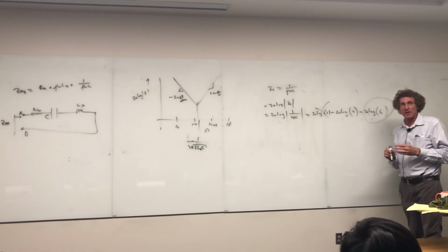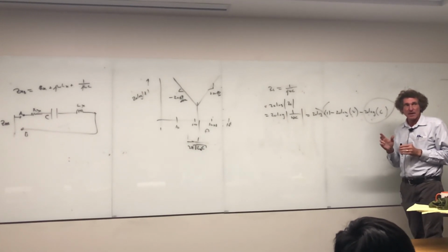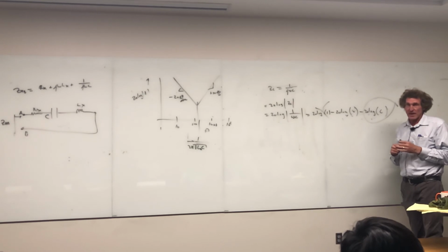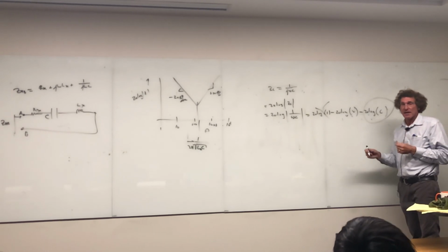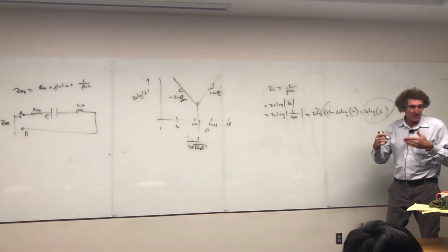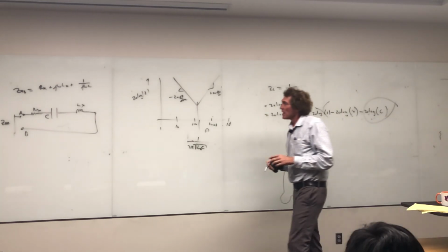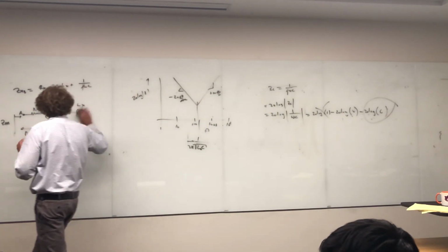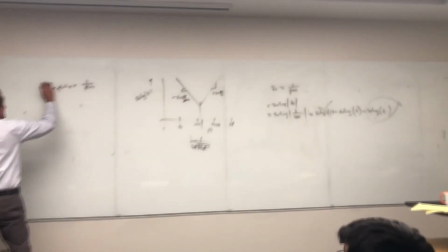That's where it comes from. I don't know, people sometimes don't see that. I want to make sure everybody does. Got it, everyone? If it went up 40 dB per decade or down 40 dB per decade, then if you went one order of magnitude like I'm doing here, you would get a total of 40. That's what I mean by dB per decade. All right. That's that.